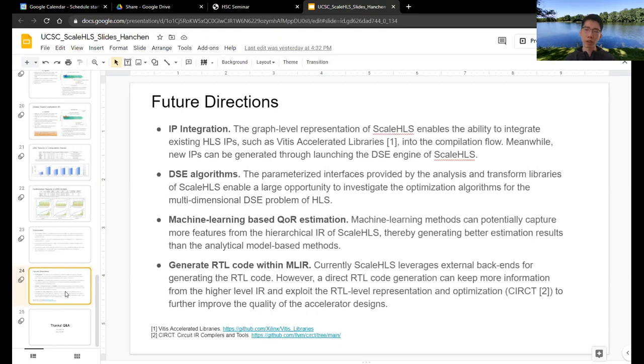But a very critical question is how do you handle pipelining, right? For now, we are also estimating the minimum initial interval that you can achieve based on two things. The first thing is the resource constrained initial interval. Because you only have limited memory ports for the on-chip memories, that will constrain the II you can achieve. And meanwhile, you will have those loop carried dependencies.